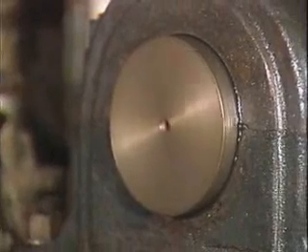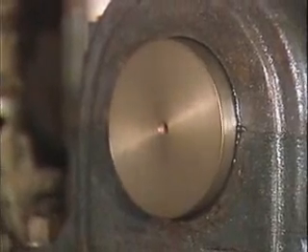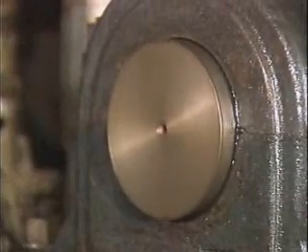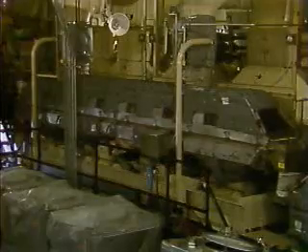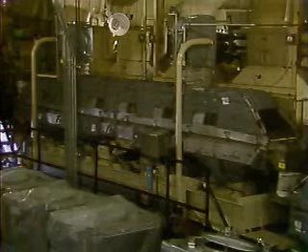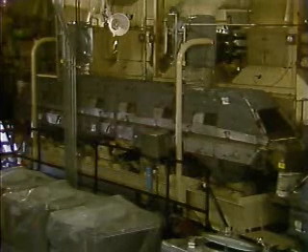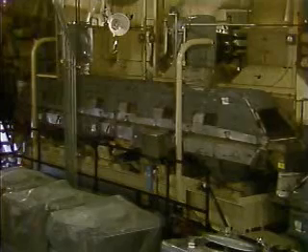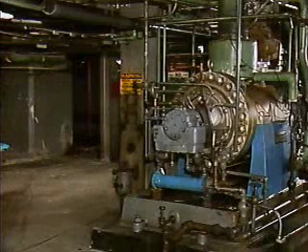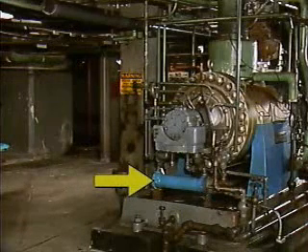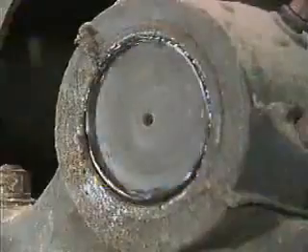Keeping the lubricant in place is important because leaking lubricant could contaminate surrounding areas or cause a fire hazard. Another reason for using grease is that grease may be required to assure that contaminants are prevented from getting between lubricating surfaces. In some high-temperature applications, such as this conveying dryer, grease with a high-temperature thickener is used to keep the lubricant in place. It's possible to use oil in high-temperature situations, but additional equipment such as this cooler must usually be provided to cool the oil.